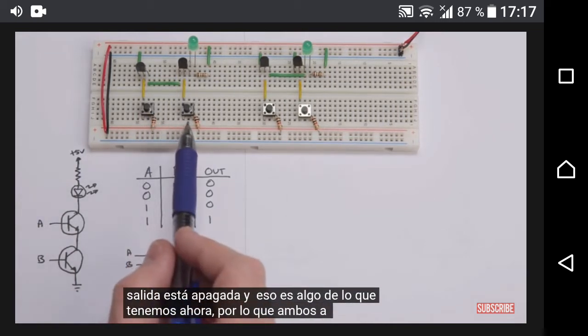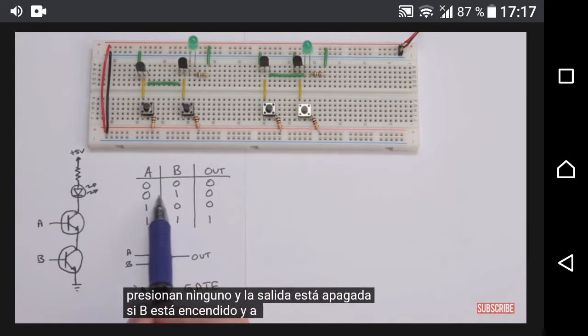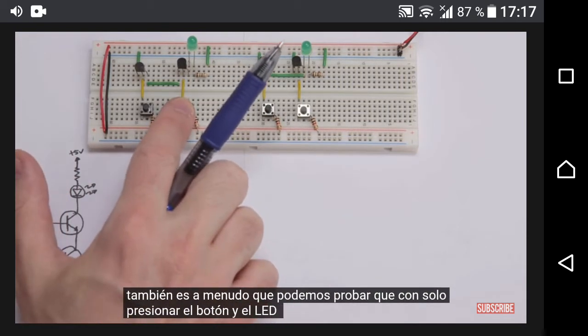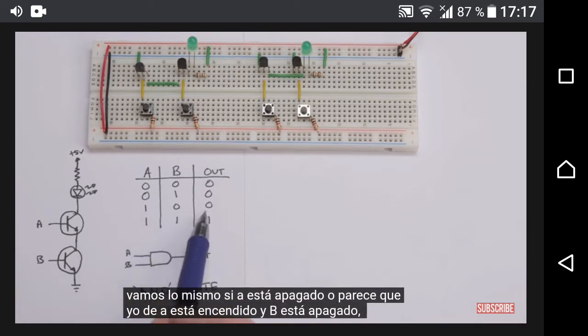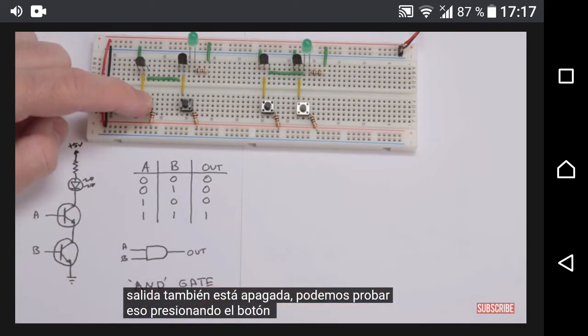So both of these are off. I'm not pushing either one, and the output is off. If B is on and A is off, then the output is also off, and we can test that just by pushing the button, and the LED doesn't come on. Same thing, if A is on and B is off, then the output is also off. We can test that by pushing the button here.